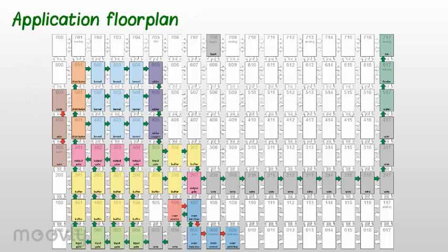This is the full application floor plan. Red arrows show flow of control signals, green arrows show flow of data. The application can be divided into several modules. There is a RAM reading module including SRAM cluster, a memory master in node 106, which reads sequentially pixel values from RAM, and two wire nodes. Since bitmap data are stored in RAM as 16-bit values, the memory master splits each value in 2 bytes and sends them downstream. When the full bitmap has been read, the master starts reading from the beginning again. Therefore, the image is continuously fed into the application.